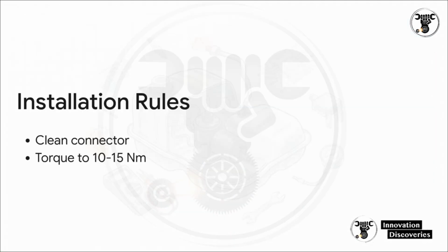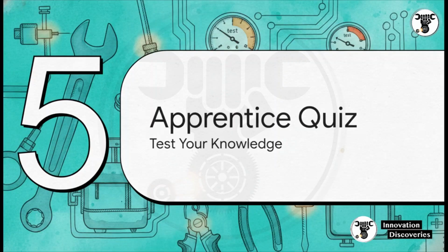And when you actually go to install it, please don't make these common beginner mistakes. First, if the old connector has green corrosion in it, you must clean it or replace the pigtail. Plugging a brand new sensor into a corroded connector is going to destroy the new part almost instantly. Second, respect the torque specifications. Most of these sensors thread right into plastic vapor lines and only require about 10 to 15 newton meters of torque. If you over-tighten it like a gorilla, you'll literally crack the brand new sensor body before you even start the car.